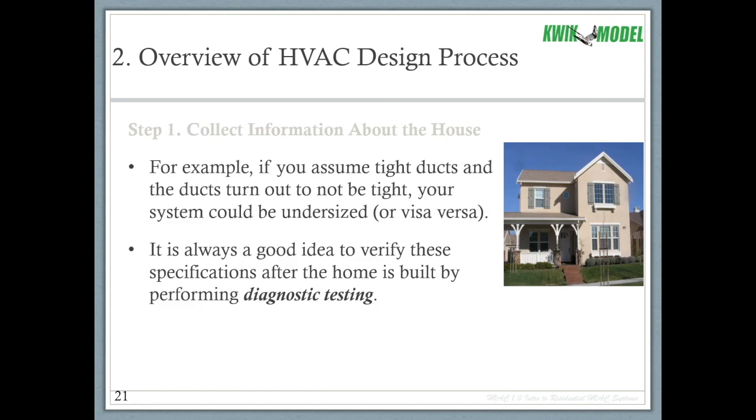For example, if you assume that the house has tight ducts and they're not, your system might be undersized. You may have way underestimated the load from the leaky ducts and you assume tight ducts, so that could be a problem. You can also go in the other direction. You can assume loose leaky ducts, but they're very tight. Now your equipment is oversized, and remember, oversizing can cause just as many, if not more, comfort complaints as undersized equipment.